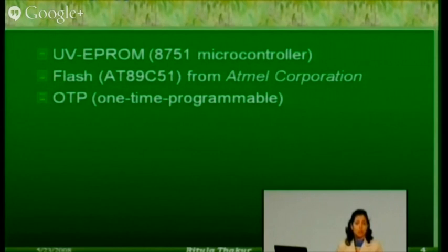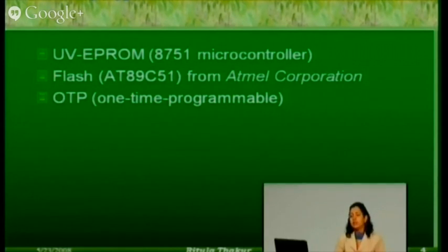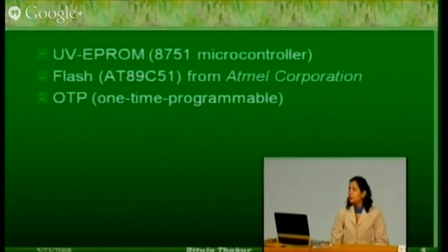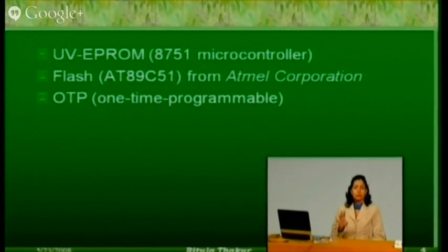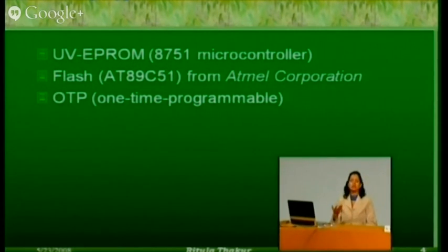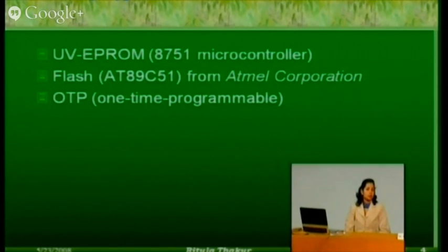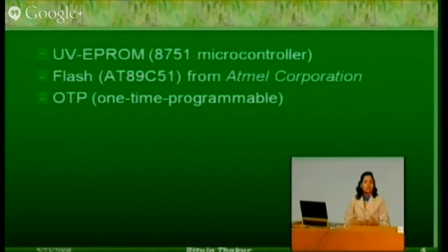Memory is very important. Now one type of memory is known as one-time programmable. One-time programmable का मतलब हो गया कि once you have written the program, you cannot make any changes to it. Okay? But while you are developing your product, you will not be using this one-time programmable. आप ऐसा तो नहीं करेंगे, because you need to debug your program and then you have to rewrite your program.